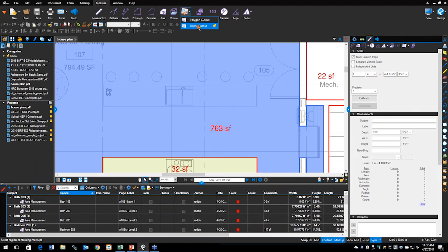It should really be designed to allow you to pick axes, which is the way most people work with ellipses. Instead, what it does is define the rectangular boundary that the ellipse fits into. So I'll show you a way to kind of fudge that and make that work a little bit better. Let's work with the polygon cutout to start with.